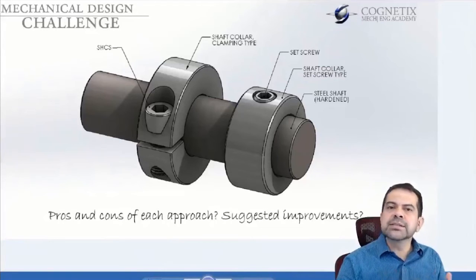For a stainless steel shaft, for example, you would probably not heat treat the entire shaft, because you don't necessarily need the entire shaft hardened. Usually we need the outside shell hardened. So you could apply a treatment called case hardening for stainless steel.